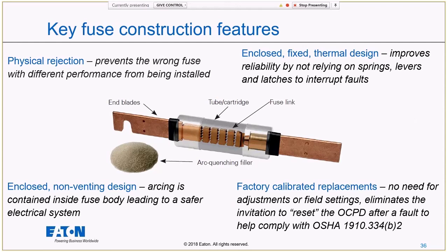I always say, installing fuses is never supposed to be a feat of strength. If a fuse is not being properly installed, if it's not going into a holder, it's probably that physical rejection feature doing its job. It's not about adding any more brute force to it.